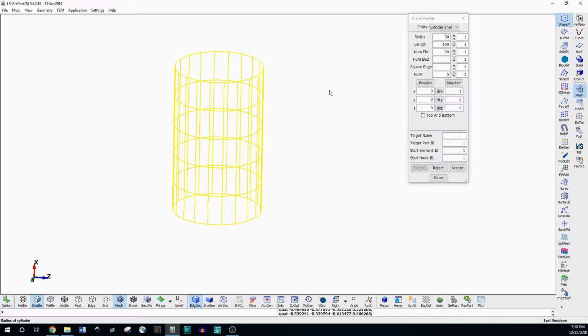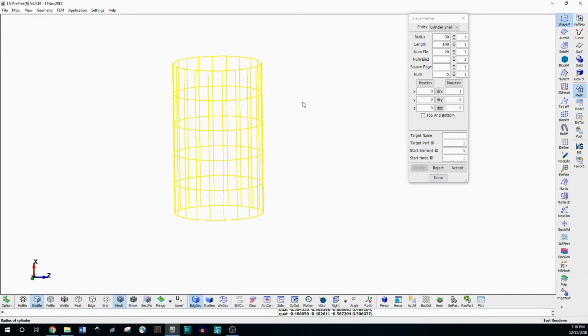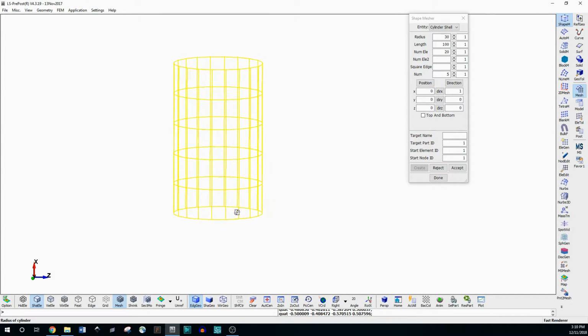This is all going to depend on whatever unit system you want to use. We're just going to use millimeters, and that's going to determine what your material is going to be and all the different parameters in there. If you need any assistance on that, just look up online different types of SAE coordinate systems and make sure your units are consistent. So if you have millimeters and seconds, your velocity is going to be millimeters per second, and so on, and that's going to transfer all the way down to force and whatever your mass is. So just make sure you're using consistent units.